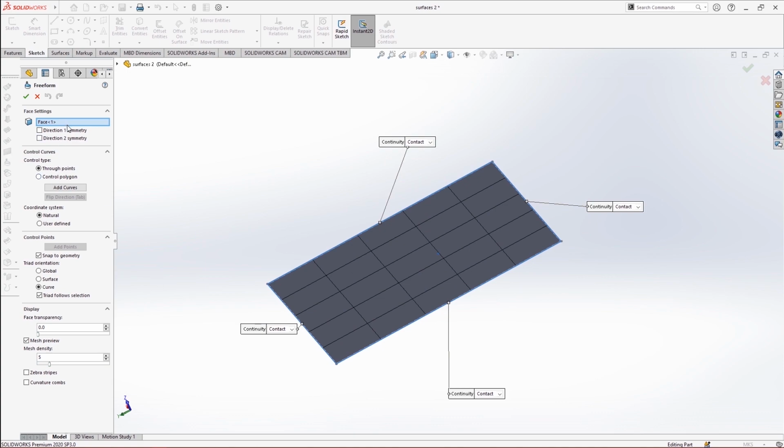First of all you select the face, then you make curves, then you select the points. Now I am adding a curve here and a curve here. Next is adding points. So I am adding a point here, here, and in this line I add 2 points only. Now when I'm out of it, I just click on add point and you are out of it.